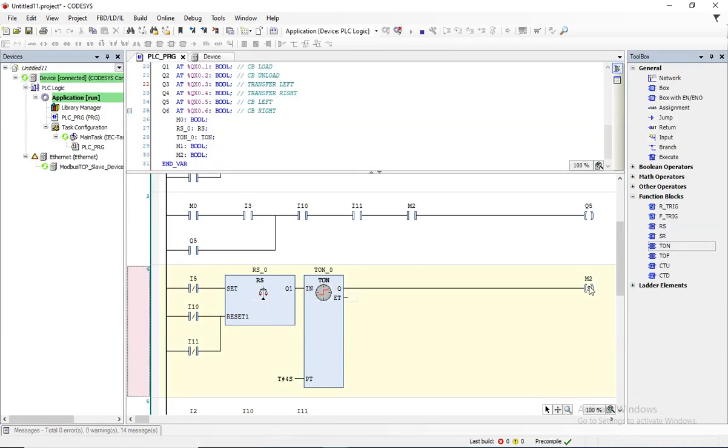So let's go the old school way, where this one goes away and gets replaced with a normal one, and then M2. Enter. And the M2 here needs to be replaced. Let's see if it can replace. No, it can't replace, which is not a problem, with a normally closed then, just like what we did in the past. And let's download.